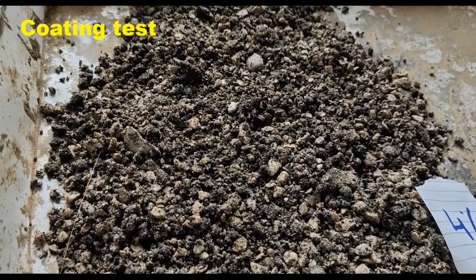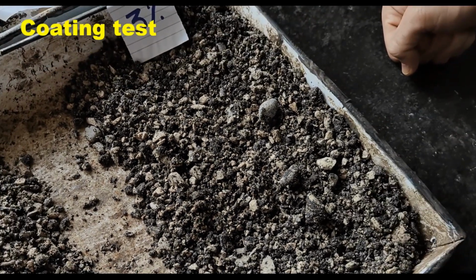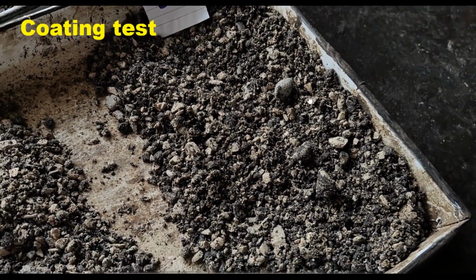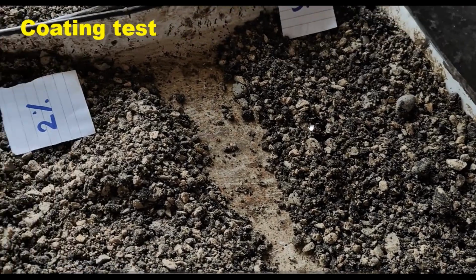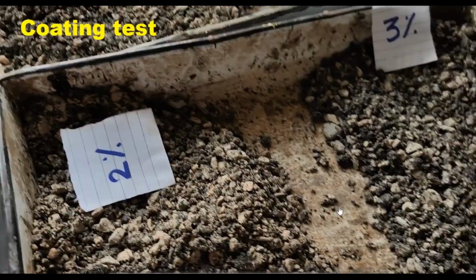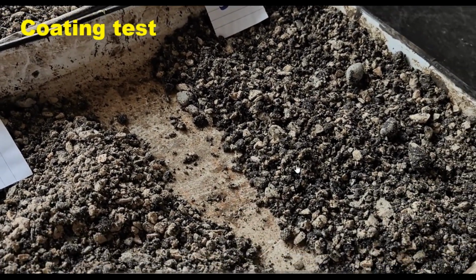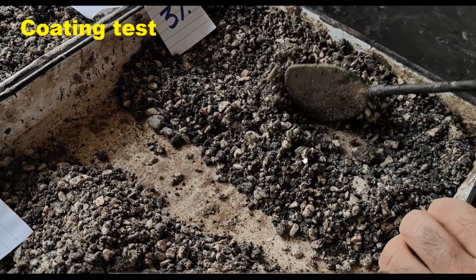Now, aggregate coating in excess of 50% is acceptable. And in this case, if you look at this sample at 3% water content, you find that the coating is more than 50%. In case of 2%, there is no coating at all. In case of 3%, it is more than 50%. You can see it.